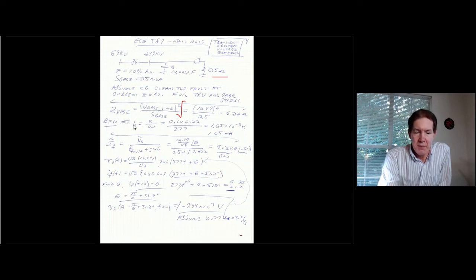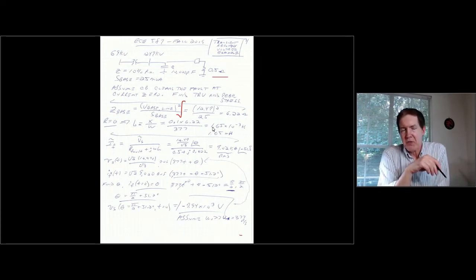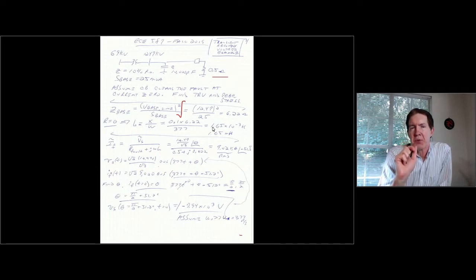What I am doing next is calculating a fault current. Now, why am I calculating the fault current in this case where I didn't do that before? Before, where I didn't have any fault resistance, I knew that when the current went through 0, the voltage source was going to be at its peak value, because we had an ideal 90-degree relationship.